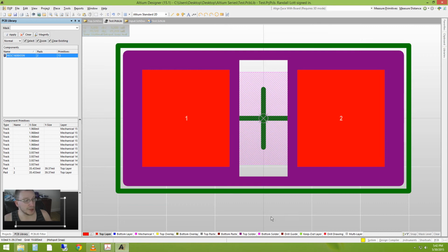Now don't get confused, because 0603 is actually an imperial code, which is used in the US, unfortunately. We still haven't gotten used to the metric system. Don't ask me. We could talk about that for a while. But 1608 is actually the metric measurement.